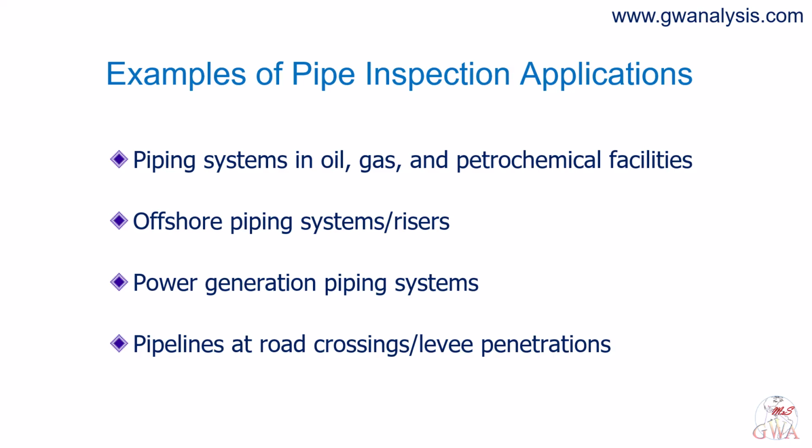First, everything we already know from conventional UT applies here: signal-to-noise ratio, calibration, the need to demonstrate coupling. Second, because it is a shear wave, liquid cannot support it, which is why the content of the pipe matters so much less than most people expect, and why water on the outside of the pipe does not matter at all. A guided wave inspector is a UT inspector. The pipe simply guides the wave a long way.